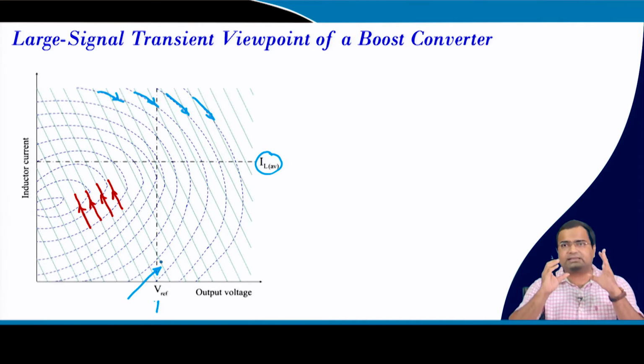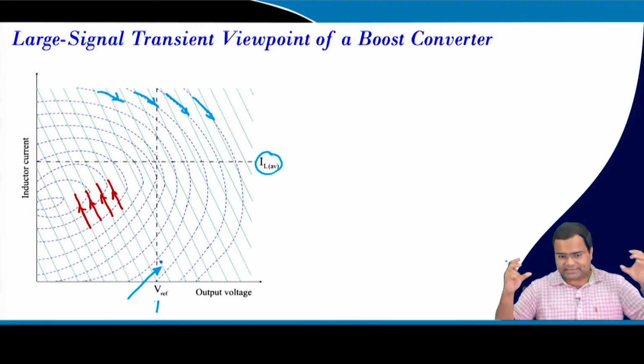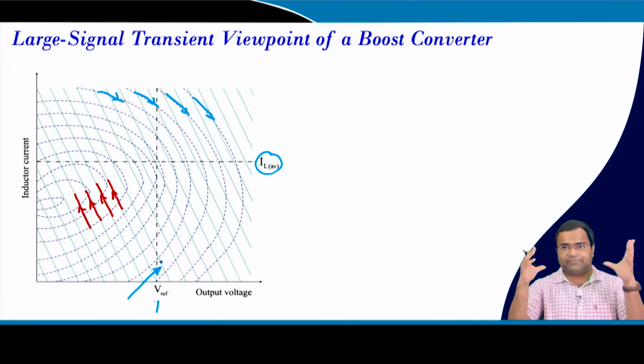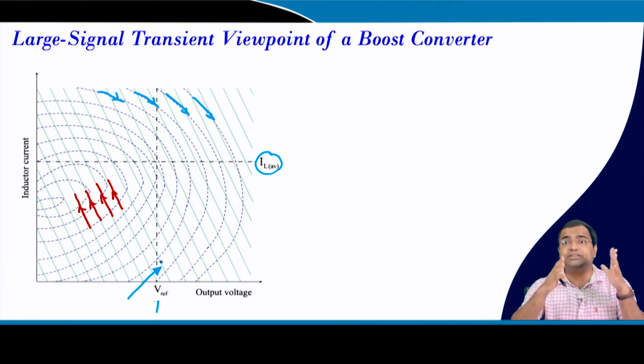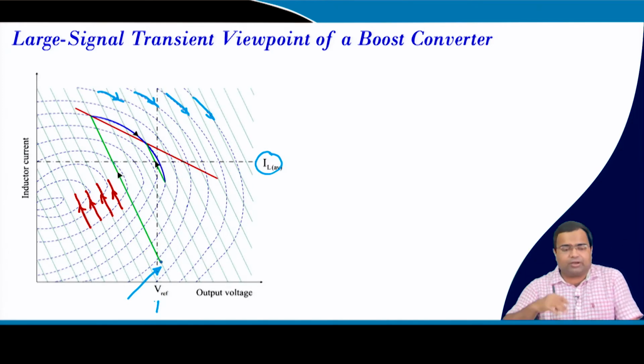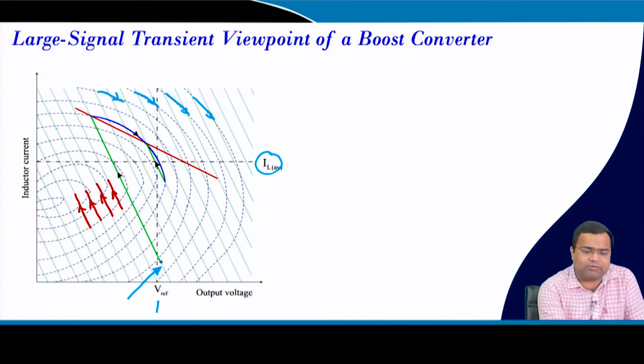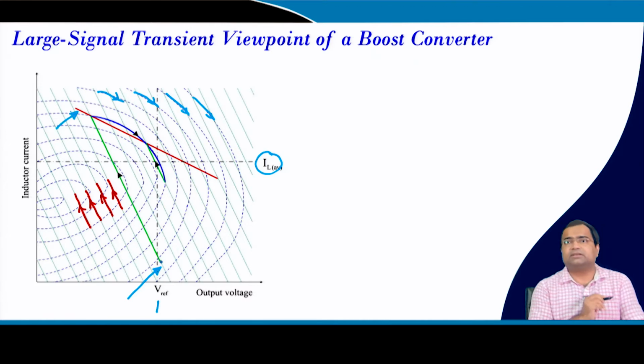And under steady state it will have an on off operation because we need a switching frequency, since it is a switching converter, right. So, if we take a surface, and we have already discussed the switching surface, the red one indicates a switching surface which is a first order surface.